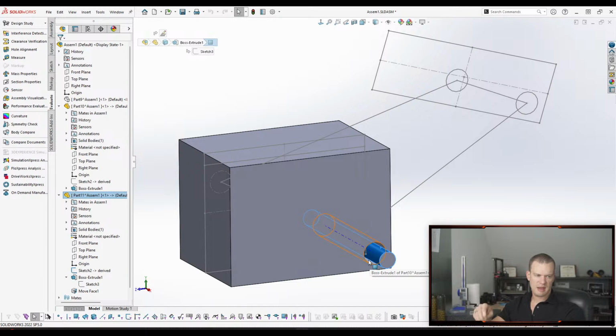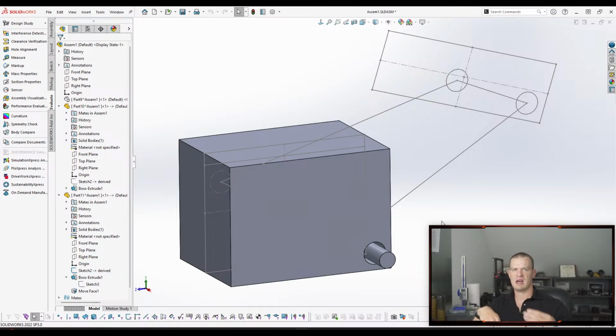So you want to keep the 1/2" pin, but make the hole larger. Yeah, in that case, it depends on how you drew it, right? And maybe this is another good point to bring up: a lot of how you design something within SolidWorks should be based on what the thing is. If I know that my pin is always going to be 1/4 inch because that's the one I'm buying from the store, right? Then I'm going to offset the gap on the hole that we're drilling, not the pin, because the pin is going to be the thing that sets it.